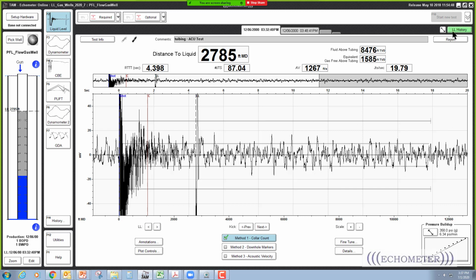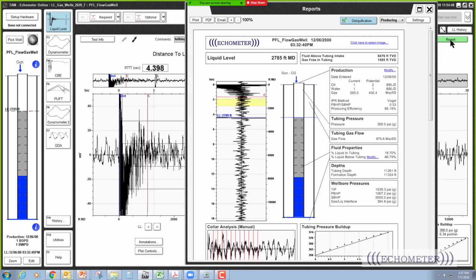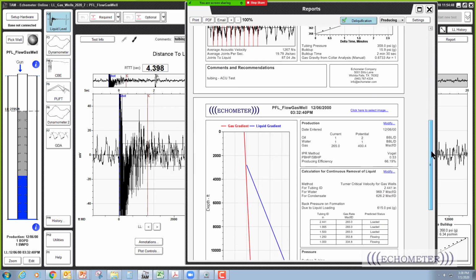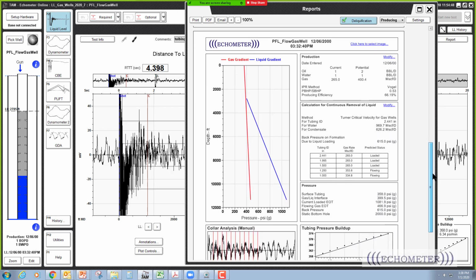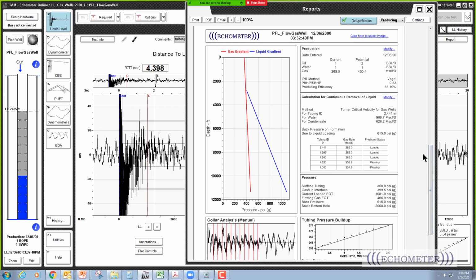If you go look at the report, this is the same report I showed in the presentation to show the well in liquid loaded form. This well has that deliquification report. If we scroll down toward the bottom, if you shoot down the tubing on a liquid loaded gas well, that deliquification button appears. I don't remember tubing size, but you can go in and select. This is showing 2 7/8 tubing, and I don't remember. Let's see if I can click here on edit.